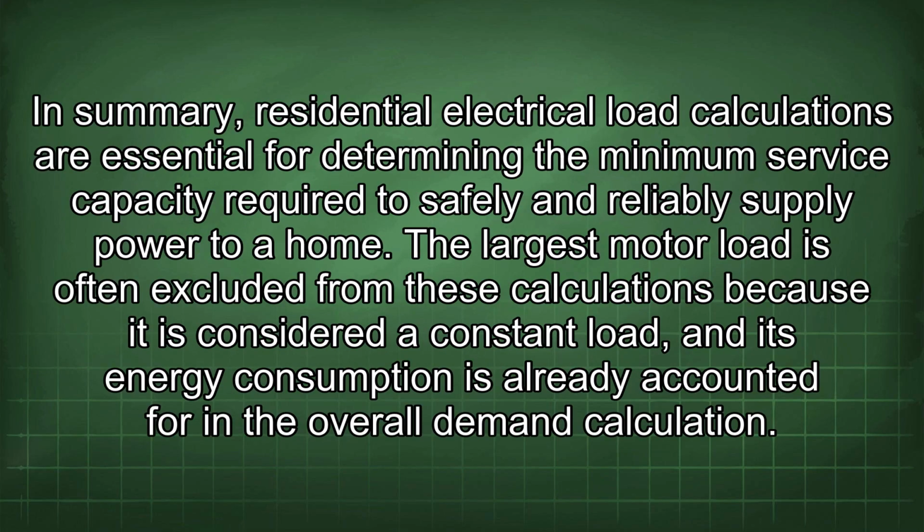In summary, residential electrical load calculations are essential for determining the minimum service capacity required to safely and reliably supply power to a home. The largest motor load is often excluded from these calculations because it is considered a constant load, and its energy consumption is already accounted for in the overall demand calculation.